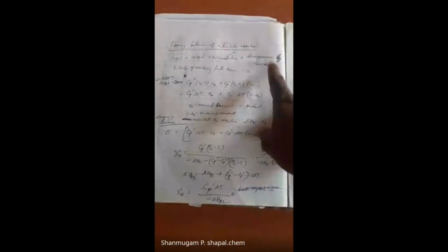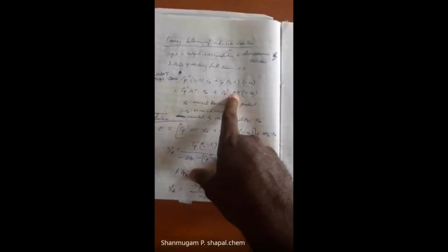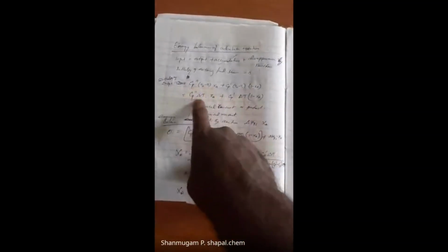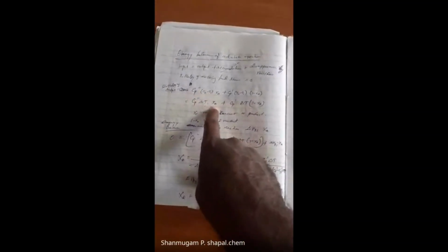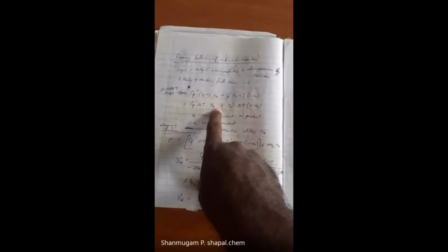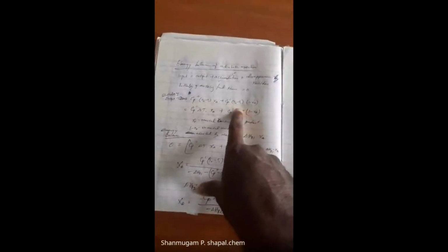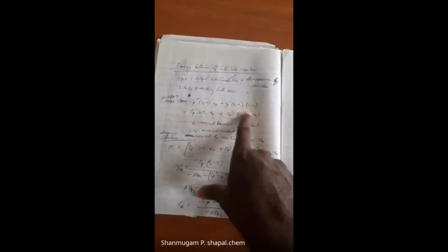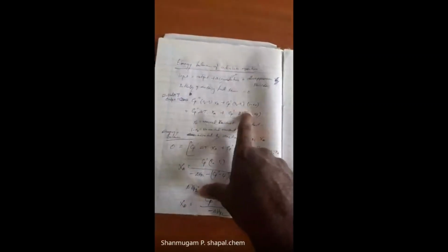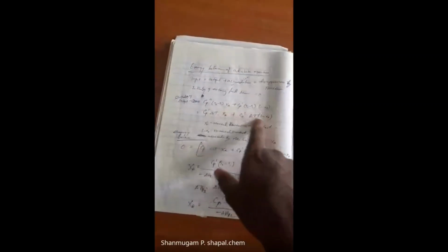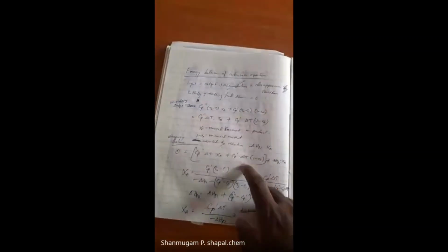So this heat should be involved here. In the case of the enthalpy outlet, it says that the actual enthalpy which goes out, with respect to the conversion of A, is the product enthalpy plus the reactant enthalpy, which is 1 minus XA, which will actually give the feed enthalpy. So this is the actual enthalpy which is going out of the system.